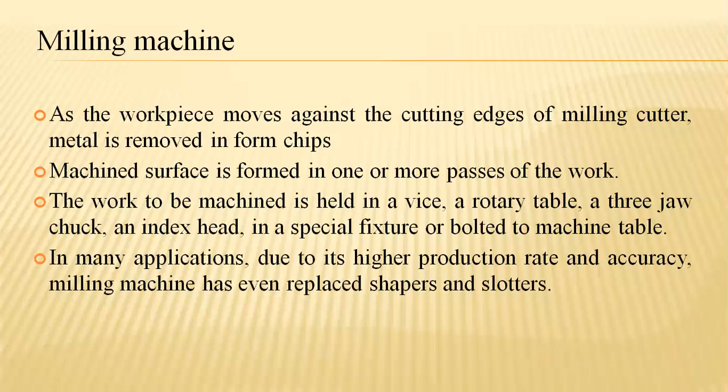This tool or cutter, normally we say, is in a static position and has a circular motion with respect to the fixed axis, and the workpiece is kept in an idle mode within the vice, which is mounted on a rotating table, and it is used to move with the help of the hand screws in to-and-fro motions and even left and right directions by the handrails.